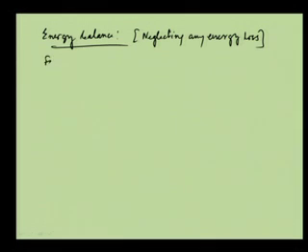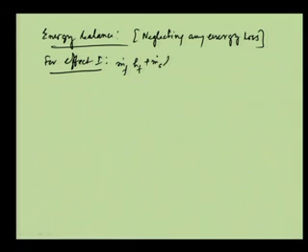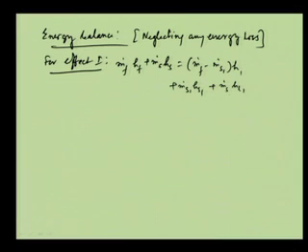Now, for effect 1, we will have m dot f h f plus m dot s h s, that is equal to m dot f minus m dot s 1, and that is h 1 plus m dot s 1 h s 1. That is the vapor, this is the concentrated liquid, and this is m dot s h l 1, this is the condensate.